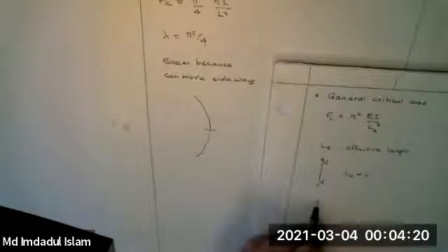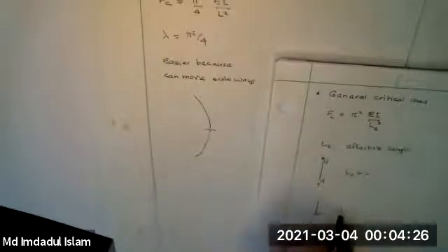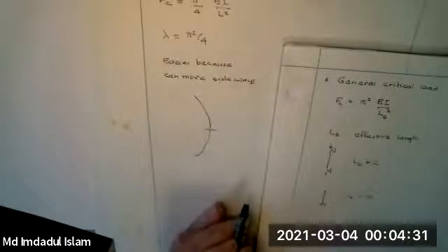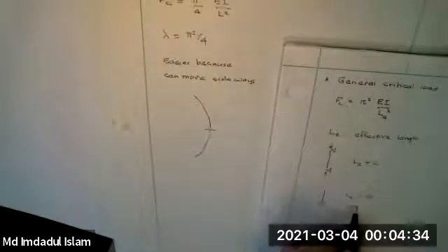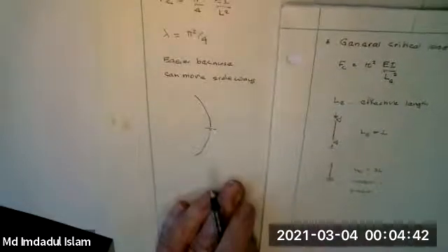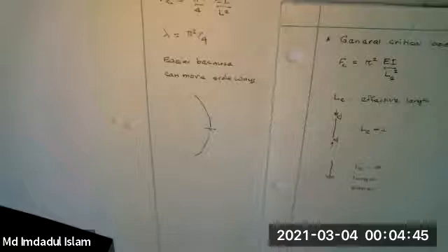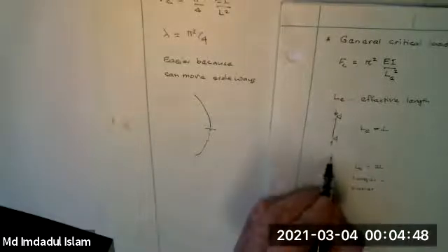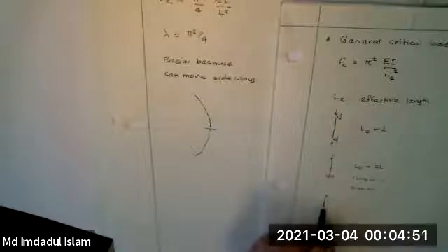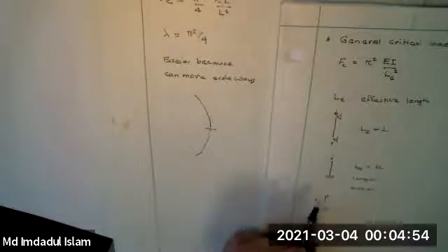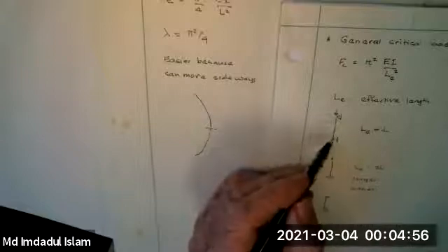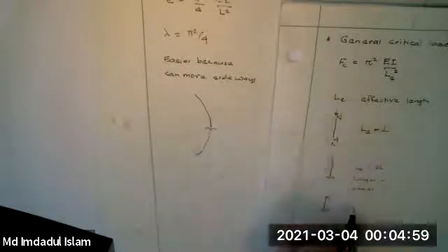On the other hand, when we did this built in, LE equal to 2L. So it's longer. The effective length is longer, like I showed you. So it's easier. If we do a combination of these two, we simply support one end and build in the other end, then you would expect this to be harder to buckle than this. And if that's the case, L goes down, and in fact it does.